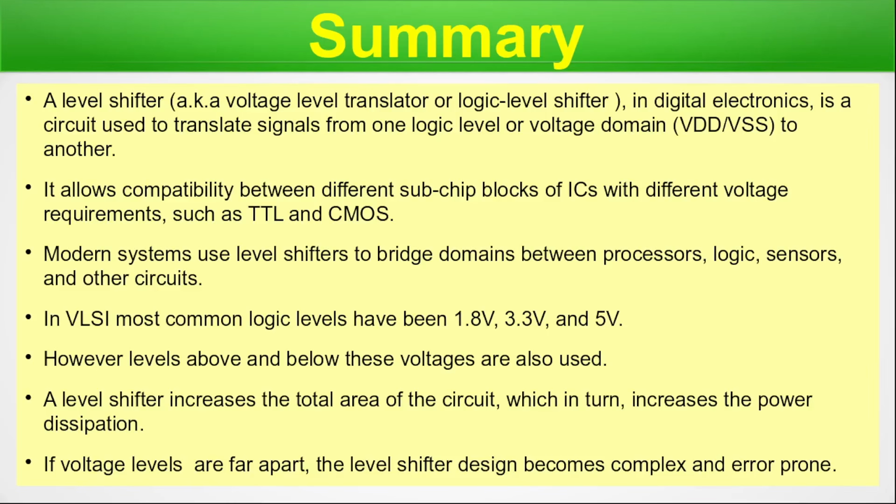If voltage levels are far apart, the level shifter design becomes complex and error prone. This is another risk, if and only if the voltage levels are very far apart. Otherwise, it is very fine and good to go. Generally, it's a theoretical point. However, these points are well taken care of when the power, performance, and area, that is PPA, is done on any StdCell library. So you don't have to worry when you are using an already characterized StdCell library that you are receiving from your StdCell vendor. We are done with this particular slide.